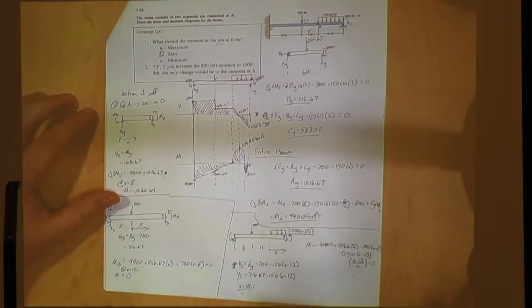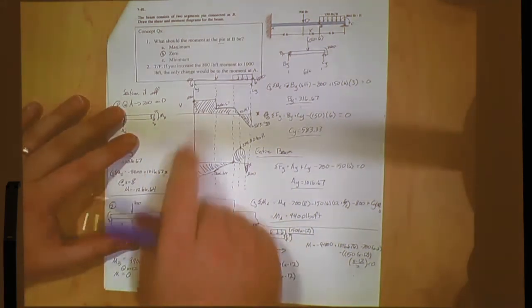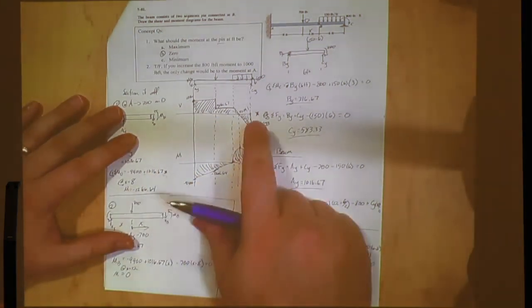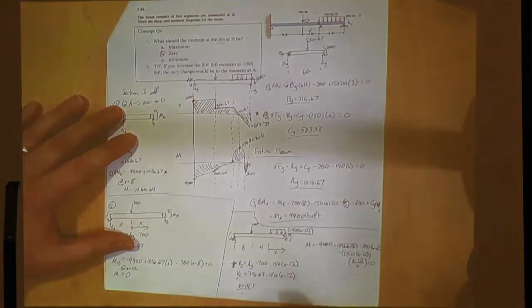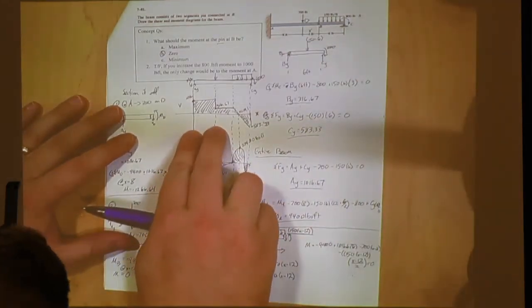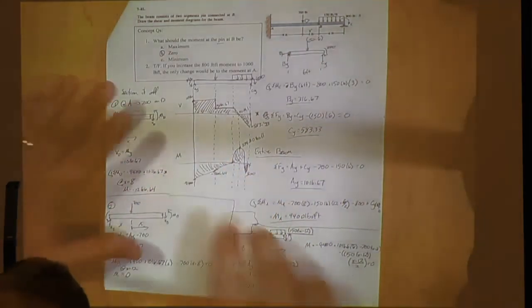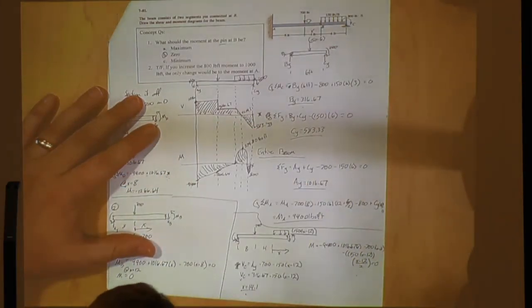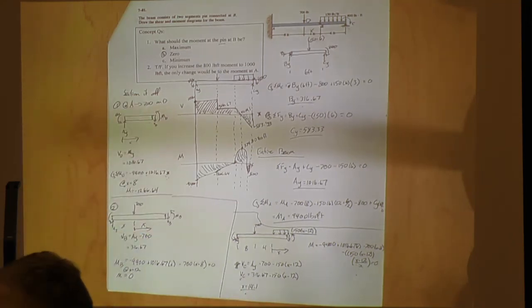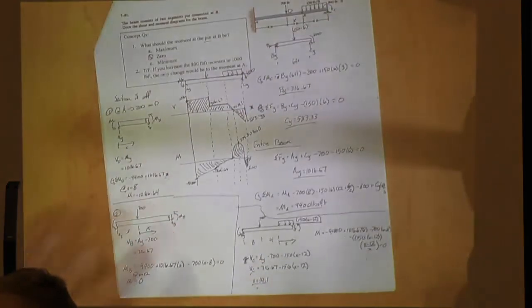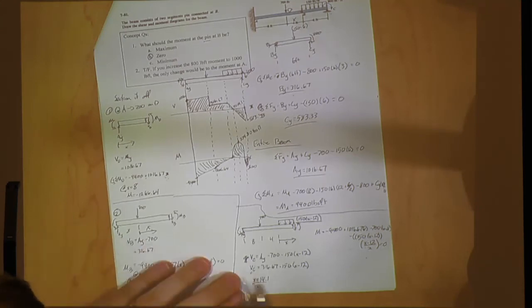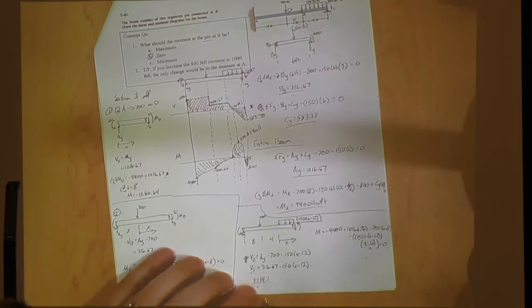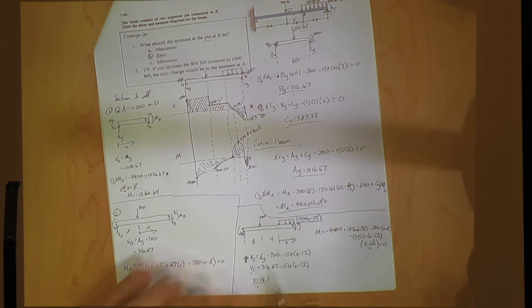It's 0 to 8, then 0 to 4, and then 0 to 6, because you're only concerned about that line with the integral method, and you don't care about anything else. That changes. But here, when you do the sections, you incorporate the entire beam. So this equation, when you solve for 0 shear, should give you 14.1. Make sense? All right. Any other questions?